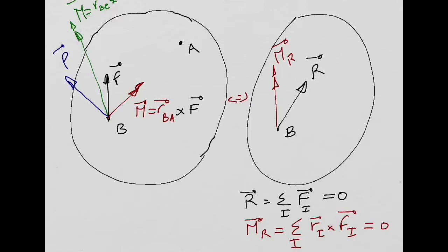Once you have everything concentrated in that point, then you can say, if these two vectors, resultant of forces and resultant of the moments, are equal to 0, then it means my entire structure is going to be in equilibrium, not only this point. That's the big advantage of this, because we built an equivalent system concentrated in one point. So basically, I transformed the equilibrium of a 3D rigid body into an equilibrium of one point. Of course, we have the moment there, but that is the big advantage of this procedure, okay? So let's do one quick example just to show you how this can be done.